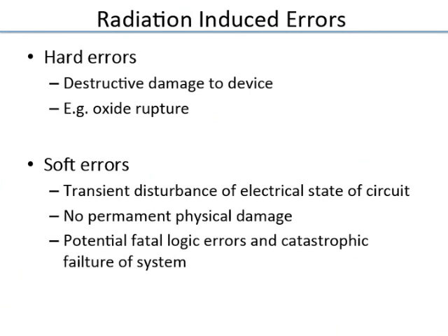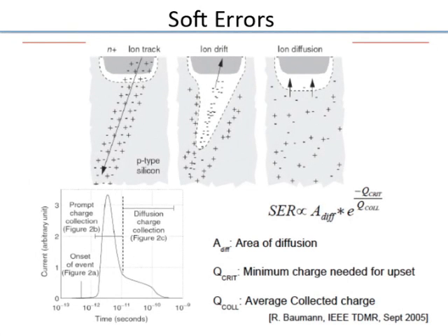So now you would say, are these ions and so on so important? Why should we worry about it? If you do some space-based application, okay, you can understand. But no, it turns out that even under terrestrial conditions, especially some of these materials used for packaging and so on, can have heavy elements which can release ions and alpha particles. And also, of course, you have cosmic radiation coming in. So we are always bombarded by these things. And as you are scaling down, the transistors and devices have become more susceptible, especially memories. And that's why I'm discussing it now here.